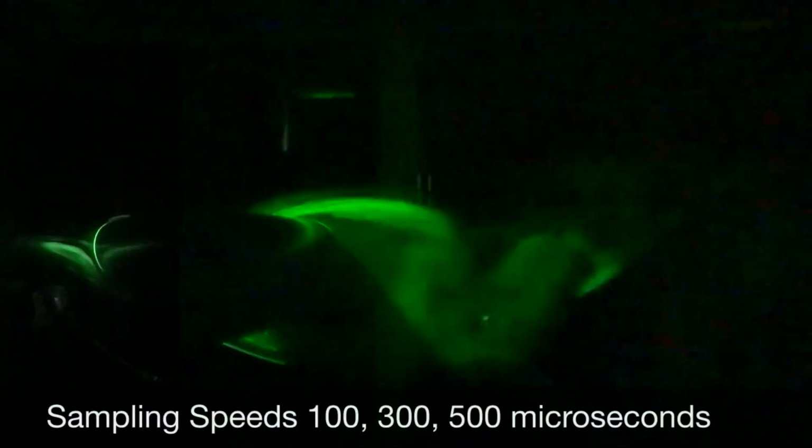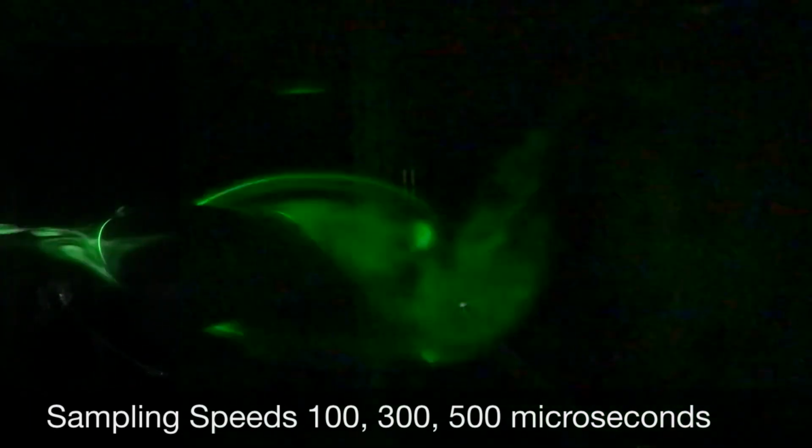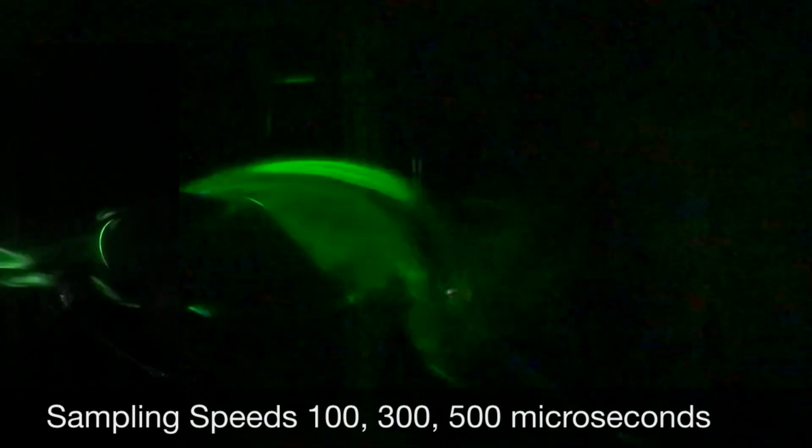Two separate test runs were used for this experiment: cylinder without trip and cylinder with trip. Within each test run, there were 3 different RPM speeds of 150, 300, and 650 RPMs. The sampling rate was varied for each RPM setting, with data taken at periods of 100, 300, and 500 microseconds. At each sampling rate and RPM setting, 3 trials were conducted. This gave us a total of 27 sets of data for the cylinder without trip and 27 sets of data for the cylinder with trip.